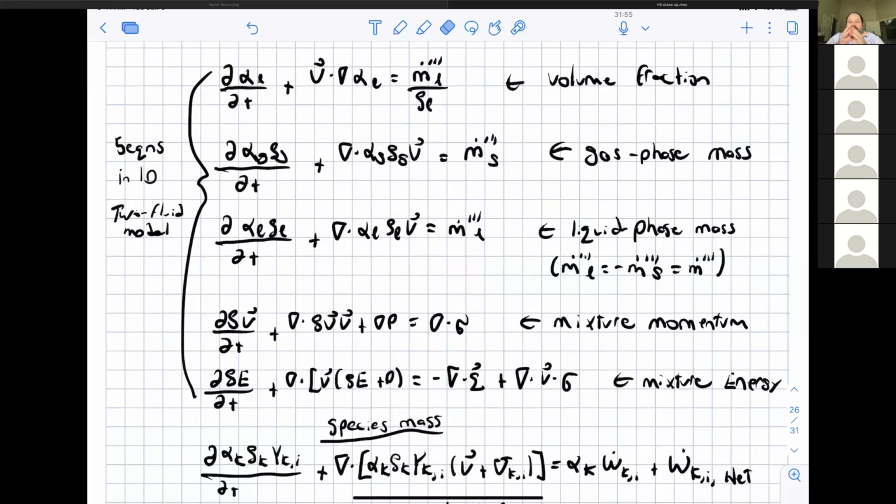And if you're not careful, those terms, if you were to compute the sound speed of your governing equations, as you do in gas dynamics, these evil nozzling terms can make the sound speed for the gas-particle mixture complex valued, which is of course unphysical. So these nozzling terms look innocuous because they're just pressure times a gradient, but they cause all sorts of mathematical problems, which we're just learning how to deal with.